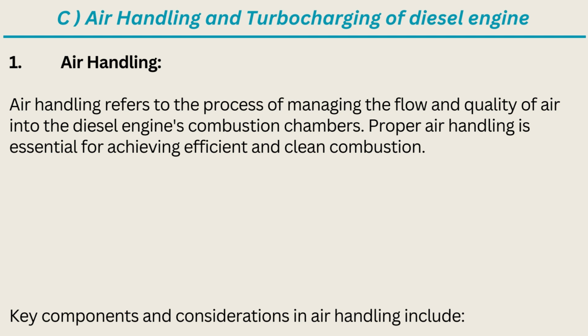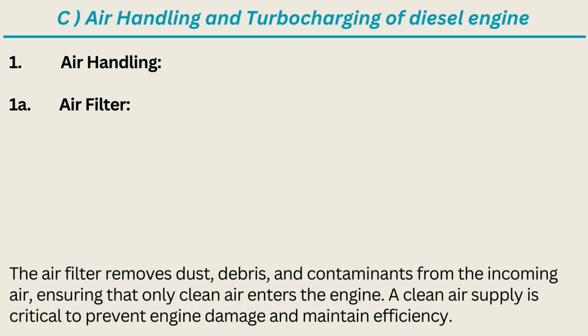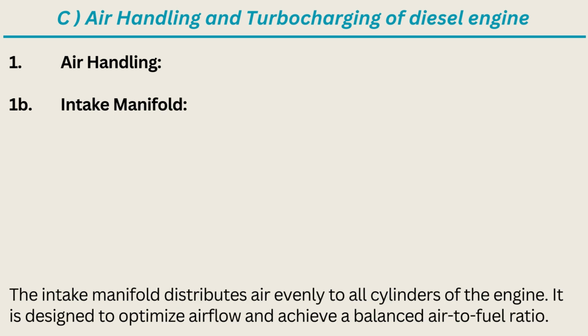Key components and considerations in air handling include 1A. Air filter. The air filter removes dust, debris, and contaminants from the incoming air, ensuring that only clean air enters the engine. A clean air supply is critical to prevent engine damage and maintain efficiency. 1b. Intake manifold. The intake manifold distributes air evenly to all cylinders of the engine. It is designed to optimize airflow and achieve a balanced air-to-fuel ratio.